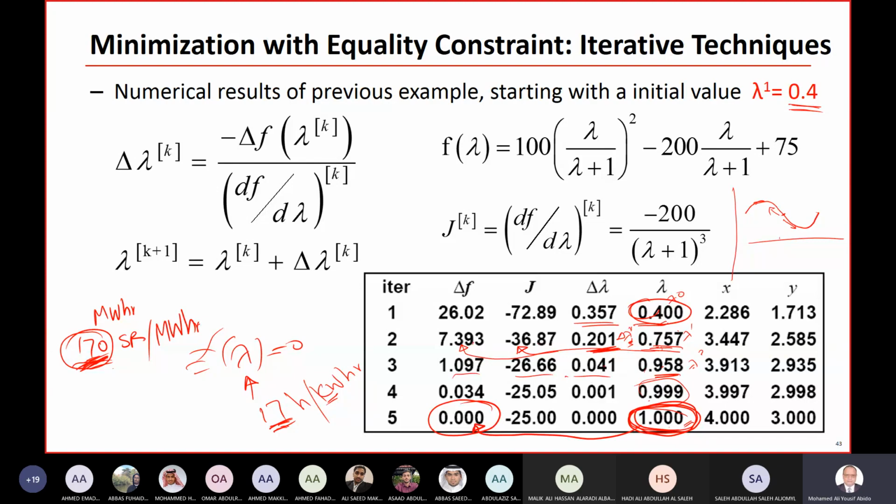There is no guarantee. With numerical solutions, like the Newton-Raphson method or the Gauss-Seidel method, divergence of the solution may happen. It is not necessarily the case every time that you converge to the optimal point. These are some stability problems of such numerical techniques. Of course, you start wisely and then you can iterate and see the best solution.